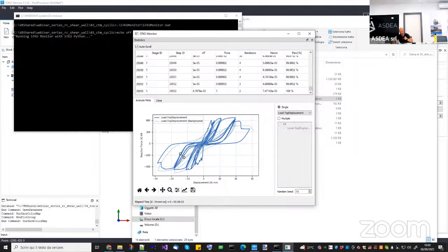Okay, so you are increasing the number of increments, so you are decreasing the time step. Now, typically, when you have nonlinear models, you think that with a smaller time step you should converge, but sometimes it may happen that with a large time step you overcome. You can actually pass a non-convergence point just because you are jumping over it.